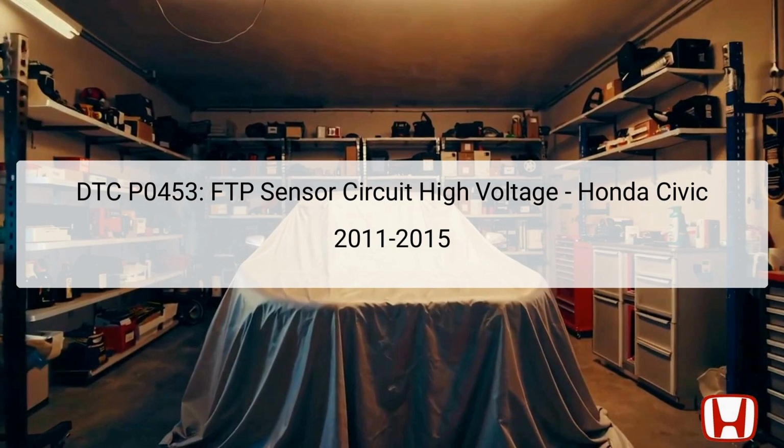The FTP sensor's primary function is to monitor the pressure within the fuel tank to ensure that it operates within the designated pressure range, which helps in preventing fuel vapor release and ensuring efficient engine performance. Essentially, the sensor sends voltage signals to the engine control module, ECM, providing real-time data about the tank's conditions. When the ECM detects a voltage reading that is higher than expected, it triggers DTC P0453, alerting technicians to potential faults in the FTP sensor or related wiring. This guide will help diagnose and troubleshoot the P0453 code effectively.